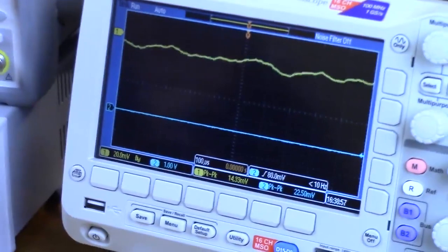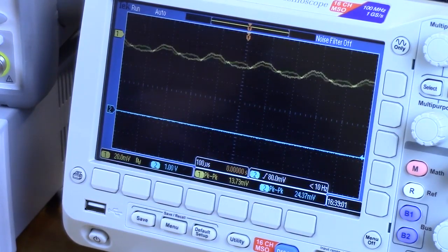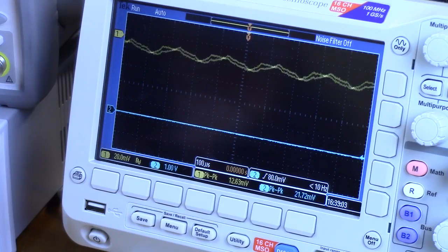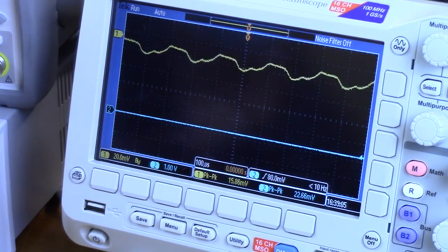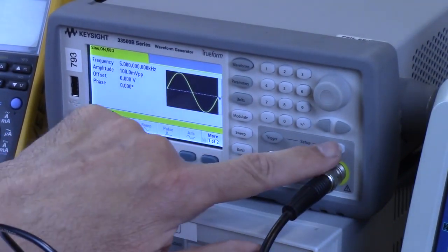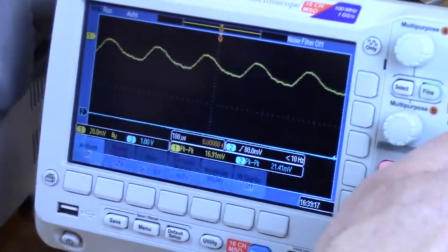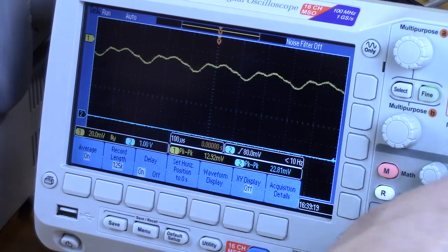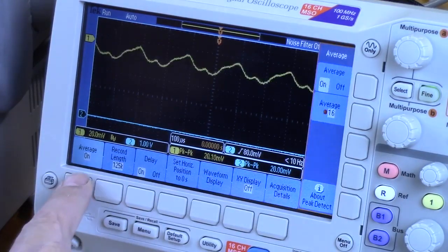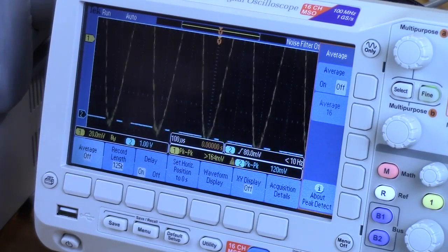okay. Now the scope is not making a very good picture of that. Let's find out why that is. Oh, because the output's not turned on. Let's see, is it on? So waveforms, channel. Okay, it looks like it is turned on. And then why is the scope doing that? Let's make sure that the averaging menu is off. Okay, it looks like it's on right now. Let's shut it off. That's better.